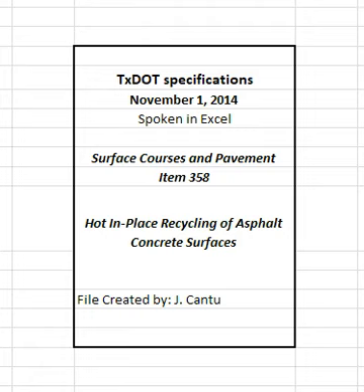Supply a list of certified personnel and copies of their current certificates before beginning production and when personnel changes are made. 4.2 Mixture Design. Design a mixture to meet the requirements listed in Table 1 using a Superpave gyratory compactor. Compact specimens at the anticipated production temperature between 200 degrees Fahrenheit and 250 degrees Fahrenheit at 50 gyrations in accordance with TEX-241-F. The target number of gyrations may be adjusted when approved.